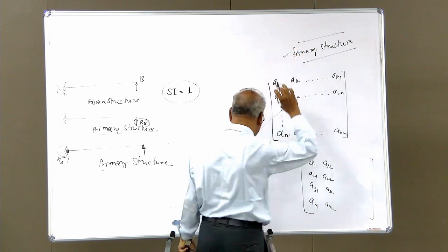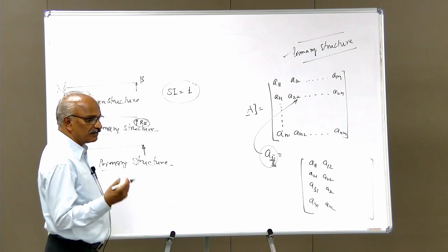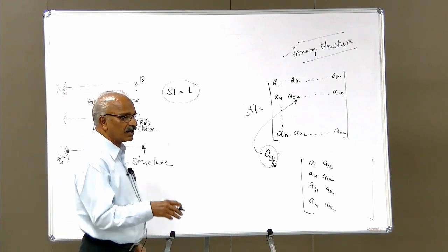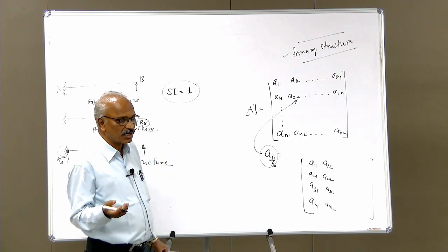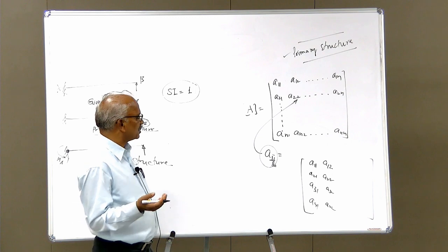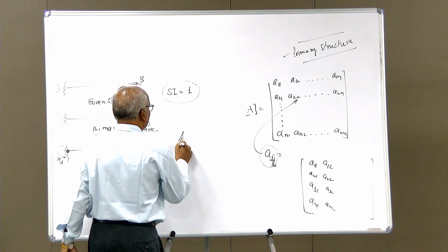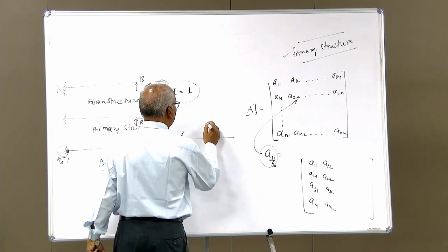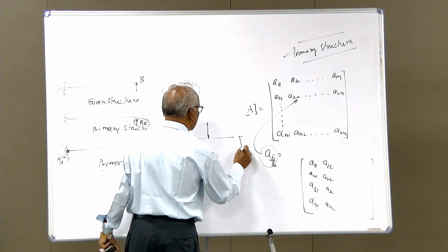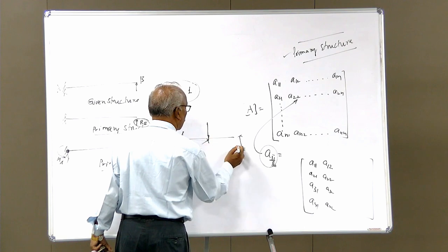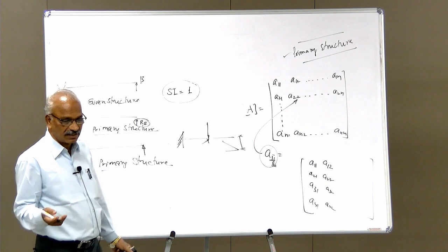in the matrix flexibility method. Then, in finding out the deflection, you have to recall whatever you have studied earlier in the mechanics of solids 1 or strength of materials. So you have to find out the deflection, A11. This is a structure, you want to apply some force here. Then you want to find out the deflection. What is the deflection here? What is the deflection here? What is the rotation here? For all these things, you will have to follow any of the methods that you have studied earlier.